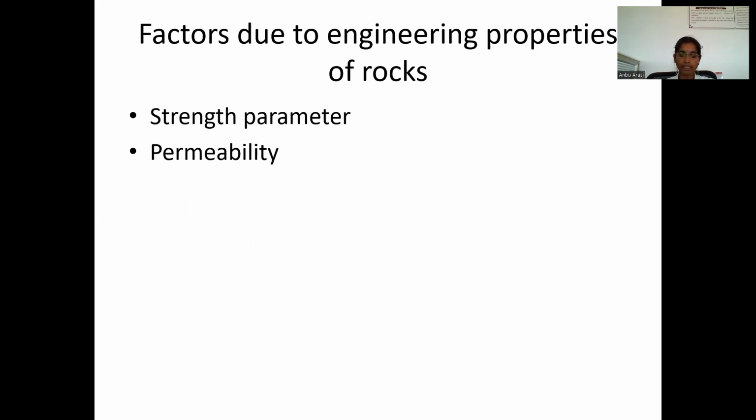Permeability: drained condition will allow the water to flow during overpressure. This flow maintains the equilibrium pressure in and out. Undrained condition acts in reverse and leads to an increase in pressure over the beds and dams. Seepage in weaker sections of soil leads to settlement of the soil.